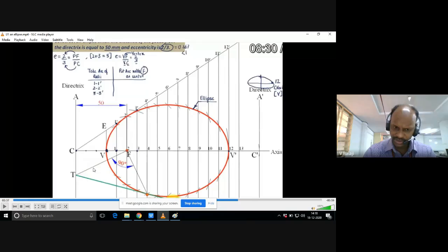Initially it is in the tight condition, right? After that, to match this particular tangent, again loosen the mini drafter knob and match one of the mini drafter scales to this tangent. Gently tighten the knob and use the other scale in the mini drafter. You have two scales. Draw one more perpendicular at this particular point. So normal and tangent are mutually perpendicular to each other. If you check with a protractor, these two lines, tangent and normal, are 90 degrees to each other. Otherwise, you have made a mistake.